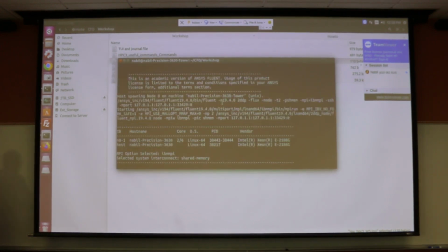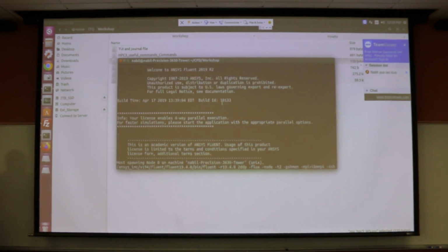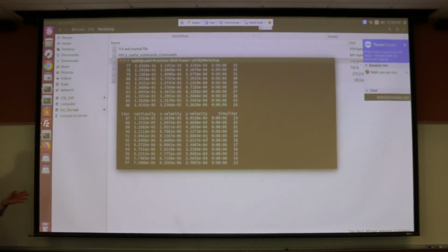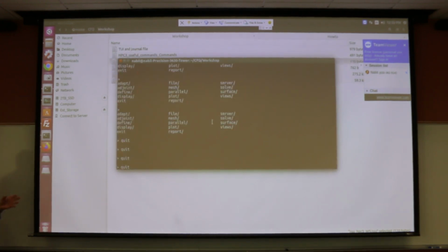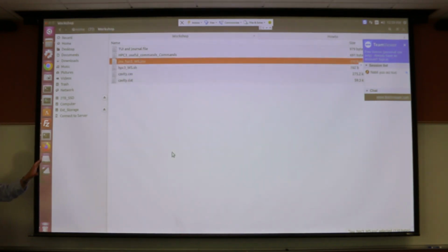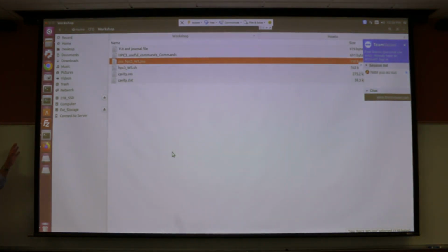Okay. Now there are some tricks and some knowledge and some experience. When I open Fluent in this way, whatever is being written in the console, or whatever is being written in the output, is not saved. It's actually inside the terminal. So if I hit close, it's gone. I didn't know what happened. Everything gone. Okay, so I cannot debug it.